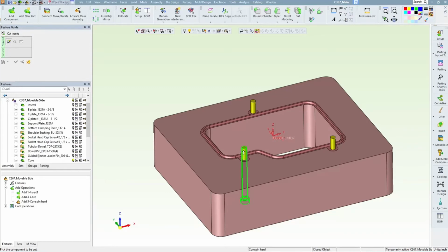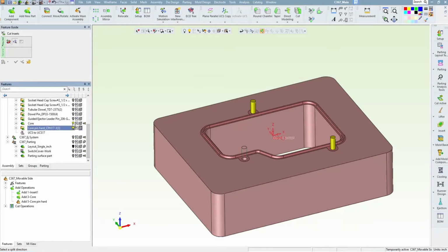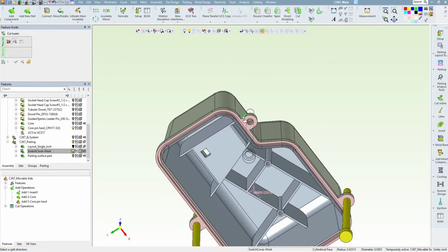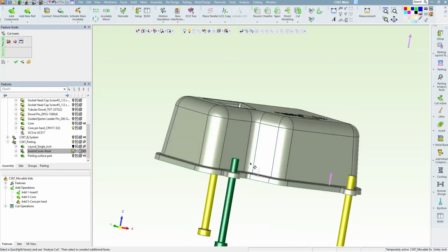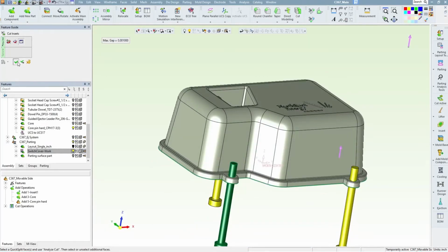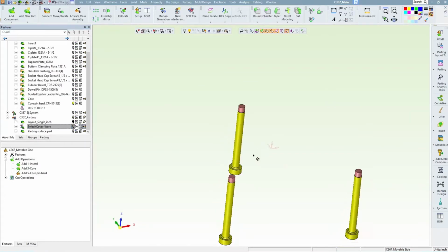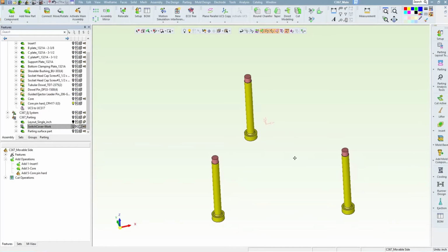Cut insert is quite simple. You start by picking the insert that needs cutting. At the second step, you're prompted to pick a split direction. And that's the key here. You put the shape on the insert directly from the work part. All you do is pick a face in the appropriate area. The function then decides which part and shutoff faces are needed to finish the insert.